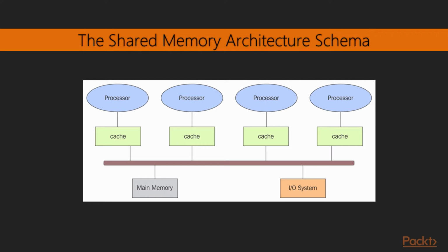Note that each processor has been associated with a cache memory, as it is assumed that the probability that a processor needs data or instructions present in the local memory is very high. The problem occurs when a processor modifies data stored in the memory system that is simultaneously used by other processors. The new value will pass from the processor cache that has been changed to shared memory.